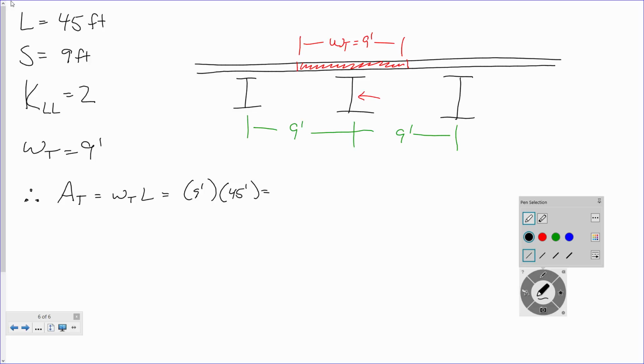There are certain situations where you can't use live load reduction. For instance, you can't use live load reduction if you're designing, let's say, the balcony in the new Dallas Cowboys Stadium, because the live load might be like 100 PSF. It might actually see 100 PSF, especially if you had a fire alarm or something. So you can't reduce that at all, because if you do and it actually sees that load, people aren't going to have a good day at the football game.